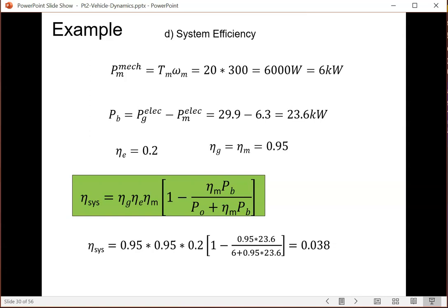But at other times, once the battery is charged up, the control system might decide to switch the engine off, saying actually we don't need the engine, we can use the battery alone. Then the efficiency will go up. The calculated efficiency at the moment is basically instantaneous. It changes over time. So that's another reason why the overall efficiency appears to be low, just the conditions the vehicle is working under.